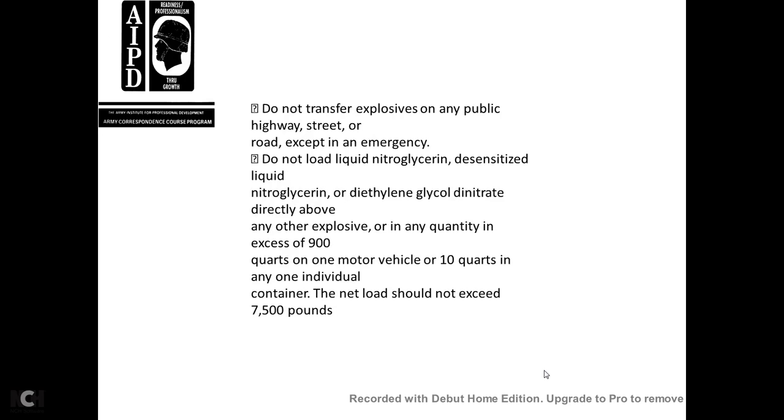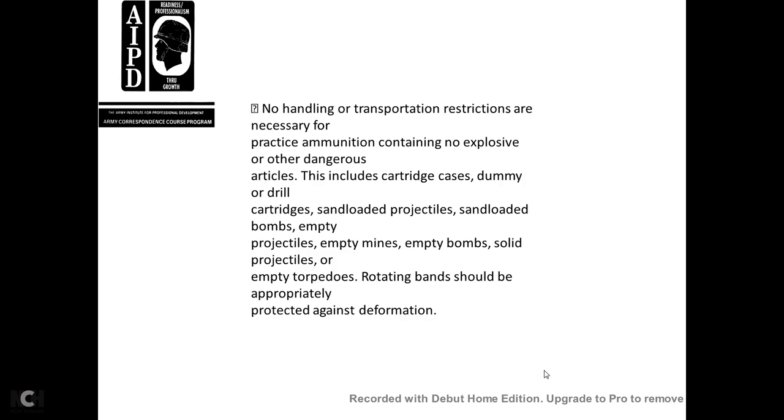Do not transfer explosives on any public highway, street, or road except in an emergency. Do not load liquid nitroglycerin, desensitized liquid nitroglycerin, or diethylene glycol directly above any other explosive, or in any quantity in excess of 900 quarts in one motor vehicle or 10 quarts in any individual container. The net load should not exceed 7,500 pounds. No transportation restrictions are necessary.